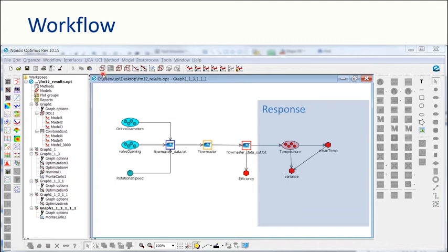At the top of the user interface, you'll notice a number of methods that can be selected. This would be a nominal method, so to run a single case, a design of experiments, an optimization, or Monte Carlo analysis. Then to the right, you see we have different models that can be created. So a Kriging model, a radial basis function model, or a number of additional user models, which include fuzzy logic, etc. Or excuse me, a Gaussian response surface model.